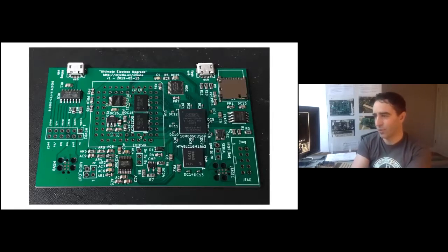It seems to also work quite well for the tiny components, and it works quite well for the big things that sit on top. I hear it's very good for things that are on top of the board and have big plastic housings which melt in a surface mount oven. They work fine on a hot plate. So it's been my assembly method of choice.